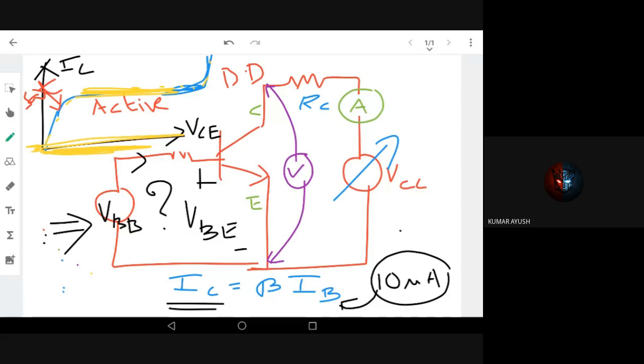You should always know what the rated current of a transistor is, and how will you get that? You'll get it in data sheets. Data sheets are manuals that the company which designed or fabricated the transistor gives you free of cost. It is openly available on the internet. Just type the name of the transistor you're going to buy or bought, and you'll get all the characteristics: the current, voltage, power, temperature variations, current gain, alpha, beta, all those things. In that transistor manual we call data sheets.